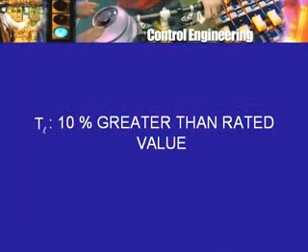Normal load will be 30 Newton meters, but occasionally the piece of material that one is polishing or whatever may be a little harder, and so it may increase the requirement of the torque. So the torque may not be 30 Newton meters, but maybe say 35 Newton meters. How much will it be? We really don't know unless one knows more about the practical drive considerations. So what one does is one makes a provision under the assumption that the load torque may exceed what is called the rated value.